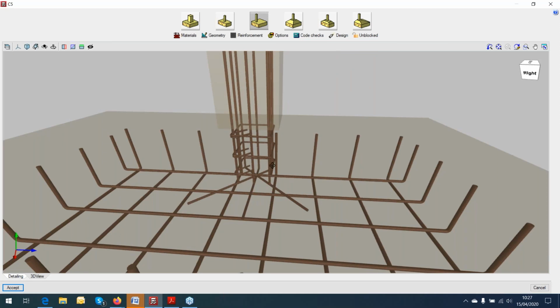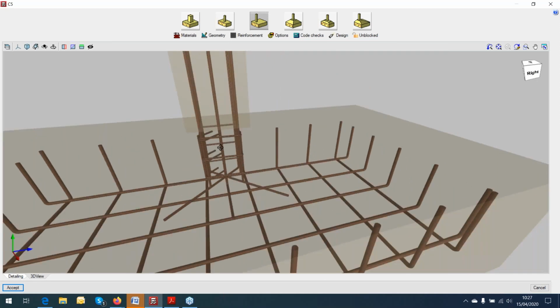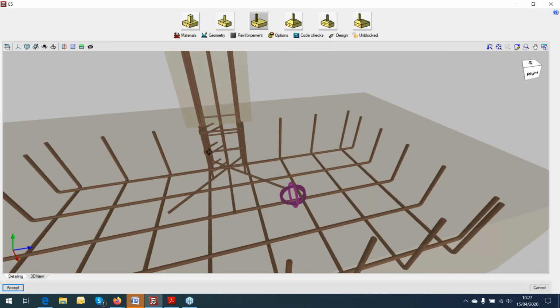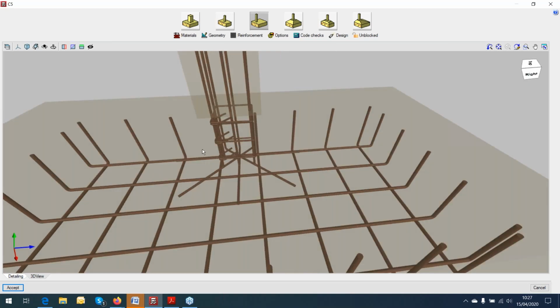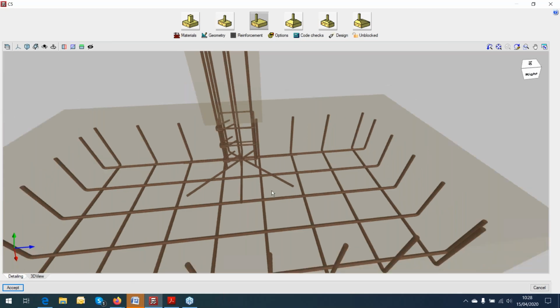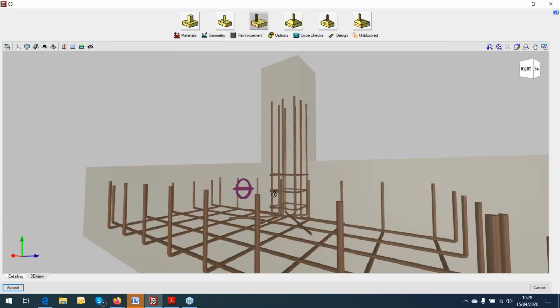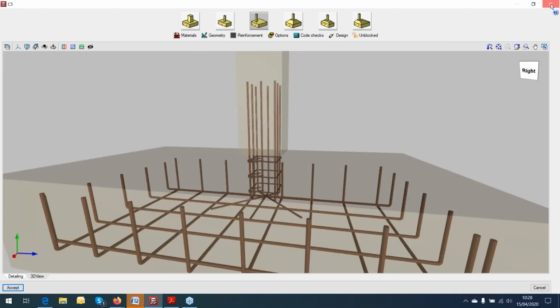So in the column designs, you can modify the bar because they give you the best bar. For example, you go for 1 inch diameter, and over there you can change it for something similar with a lower diameter, and in that case, you can get a better geometry result. This is one of the solutions.